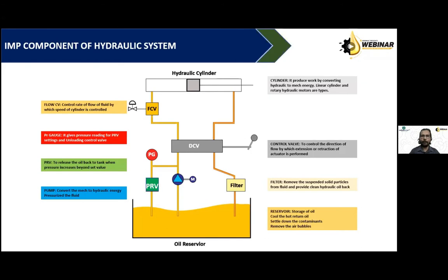If we maintain the oil quality, then these pumps will last for years and years, because these pumps are designed not to have any metal to metal contact during their operation. So if there is no metal to metal contact, there is very little chance of wear out of a component. But contamination will break the film, metal to metal contact will happen, and they will damage the pump.